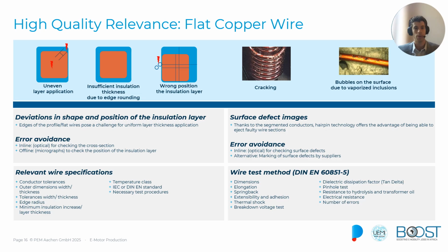We get into trouble in the bending or stripping process if the copper core is not correctly aligned within the insulation cover, or the insulation surface is damaged in any way. These errors lead to electrical short circuits and scrapping the whole stator after the electrical testing, which is the last process step.